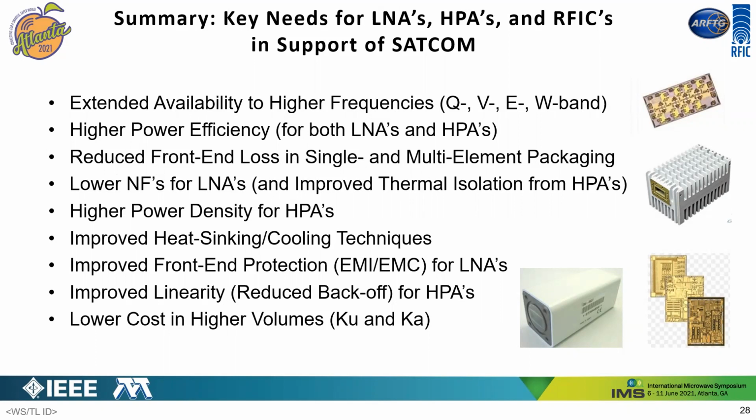We're moving to higher power densities for the HPAs. This is a trend to be able to support the higher EIRPs and higher data rates. We alluded to improved heat sinking and cooling techniques, and there are a lot of creative solutions coming in that area. Improved front-end protection. I didn't mention too much about that, but particularly in cases where the LNAs are distributed, maybe we have 1,000 LNAs, they need to be resilient to be able to operate through and survive high EMI and EMC conditions. Improved linearity, which would equate to a reduced backoff in the HPAs.